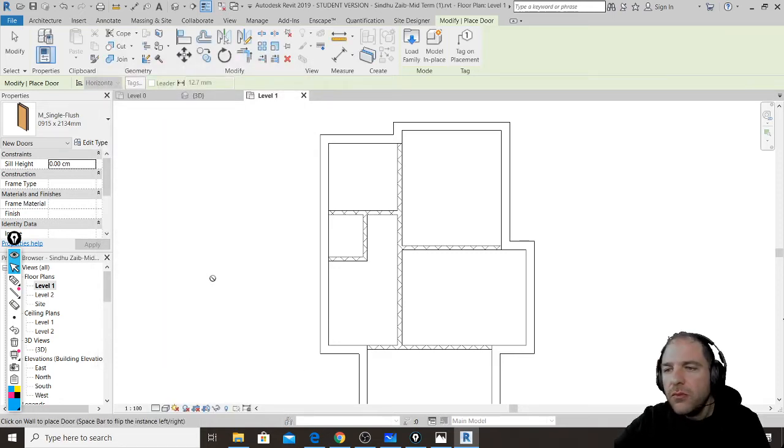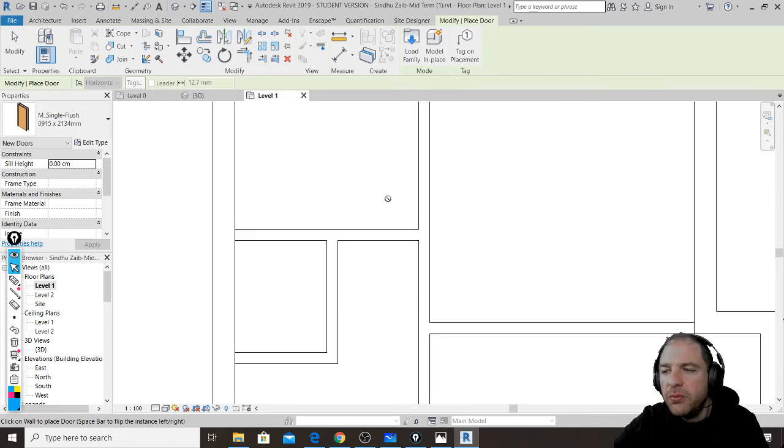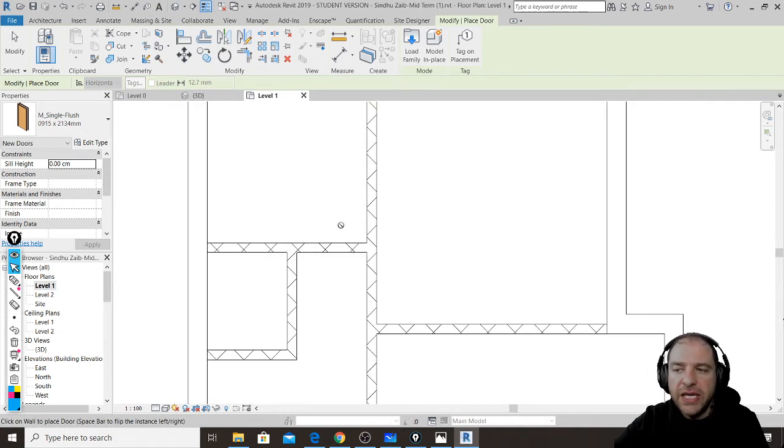If you select the door and you move your mouse, not very zoomed in, but more or less at this zooming level, you will discover that at a certain point, look, I am free to place my door where I want, but if I do this with a little bit of attention, I can see that when I move my mouse, at a certain point, look, it happens now, boom, the door is snapped to a weird point.